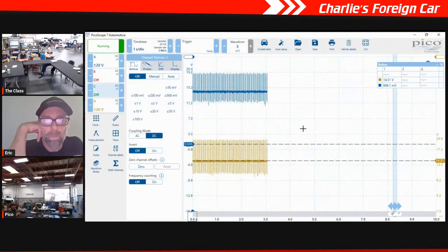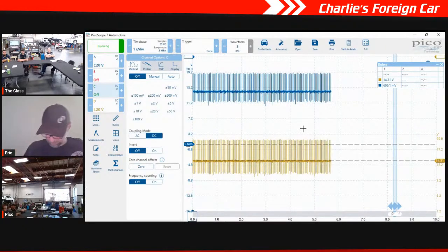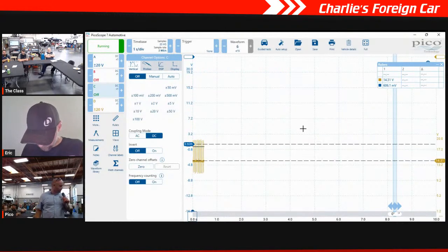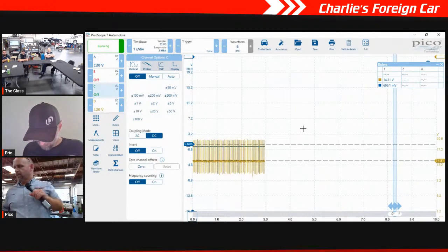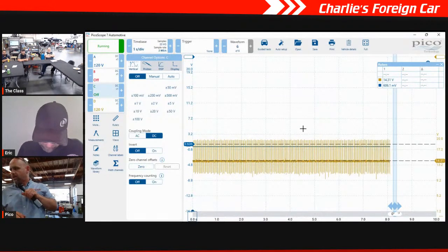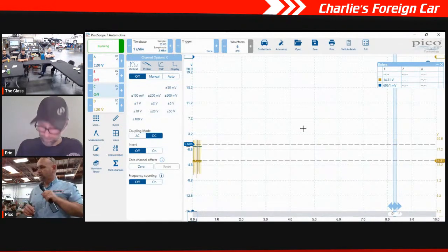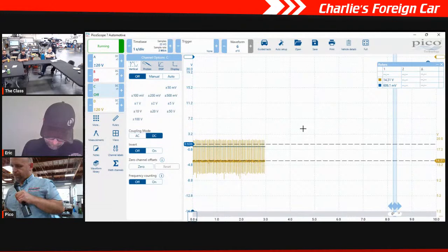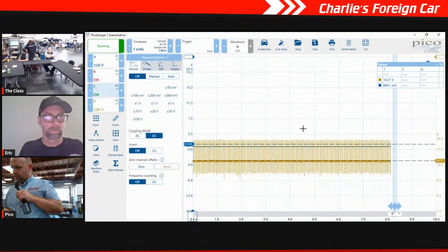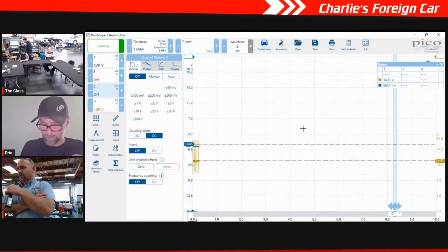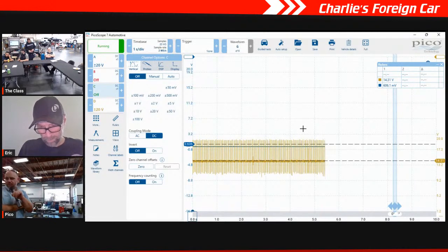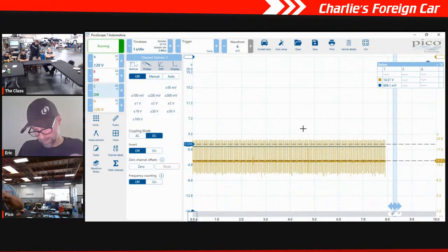So we could ground that one. Outlet cam adaptation or angle? We're looking for angle. Yeah, and I think I'm expecting it to go to 25. No, on the intake, not the exhaust. It only gives us 3 for the outlets. Okay. But I have them all up. Go ahead, and so right now the outlet camshaft adaptation is 75 degrees.